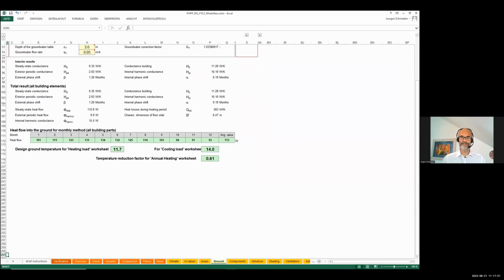And in these climates, the old method occasionally would give strange results, so that we are now explicitly combining the heat flows from winter and summer, heat going into the ground, heating up the ground, saving energy there in summer. And then in winter, that heat would be released and going back into the building. This is now all interconnected and solved iteratively, which gives a more reliable result for any type of climate whatsoever.